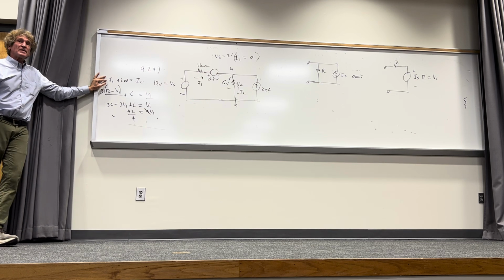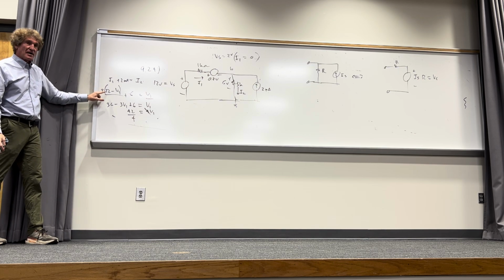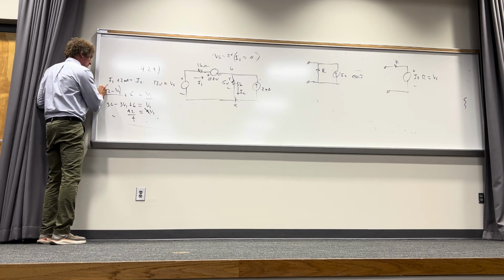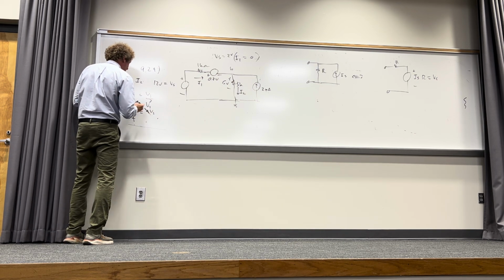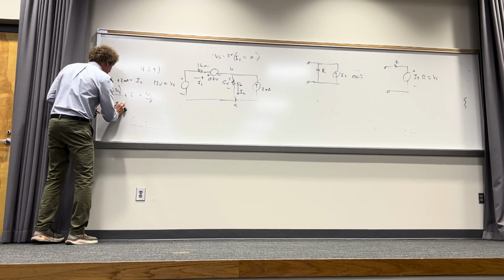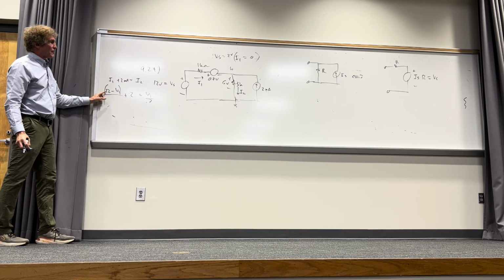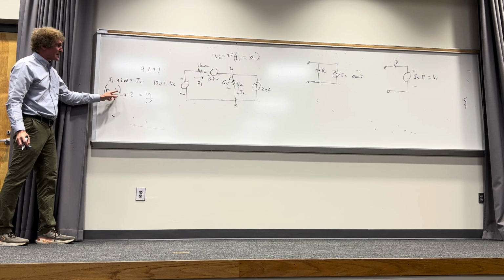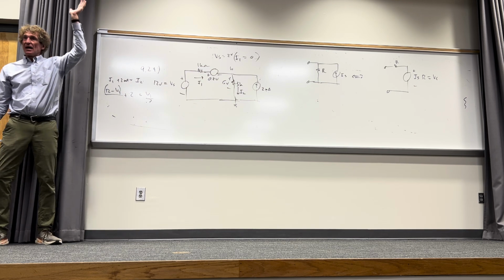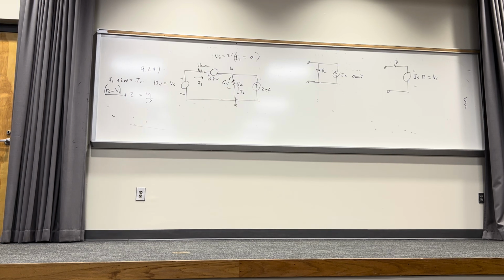All right, the only thing that changes is what here, right? Well, I'll get rid of the 3, make that 2, make that 3, and let me just talk my way through this, and I think you can see. Now instead of 12 minus V1, it's going to be 12 minus V1 plus 0.7. How many see that? You're going to have to account for the 7/10 of a volt. Do y'all see it?